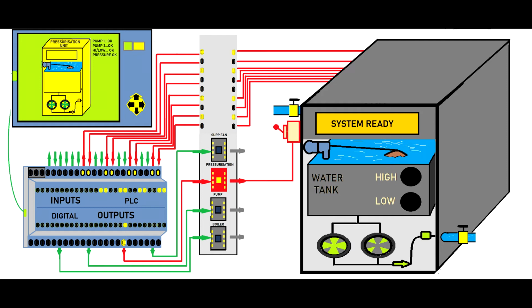Taking the front lid away, on the top you will find the water tank, and you have a floating valve. You see something floating on the blue water. That's the main intake floating valve. When the tank is full of water, that floating valve will be restricted, so the water will not go in. But when the pump starts consuming the water, then that ball goes down, allowing the main water to fill the tank again.